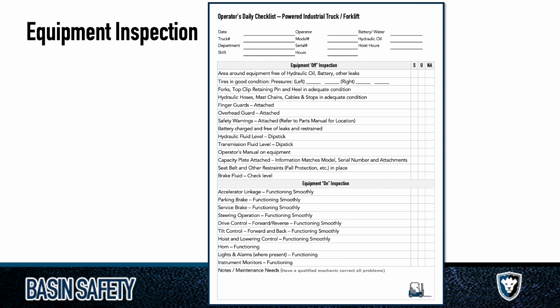And some things, like, hey, the seatbelt clicker, it's not easy to get in there, but I can get it in there. That's not shut the forklift down, send it back right away, right? As long as it clicks in and it's working, it's fine, but still notate it. Now, if the hydraulics are leaking and you can't lift anything, don't keep going with the forklift. So there's going to be a little bit of operator decision-making involved in this as far as how serious a condition or a problem is.